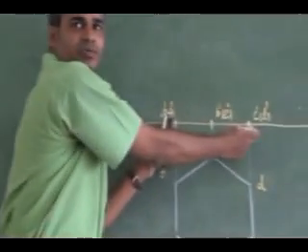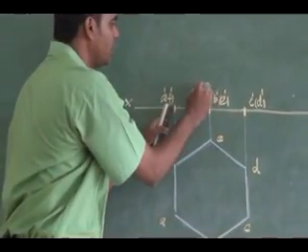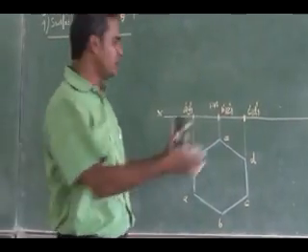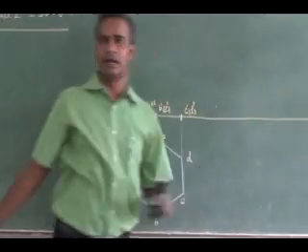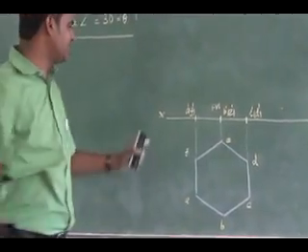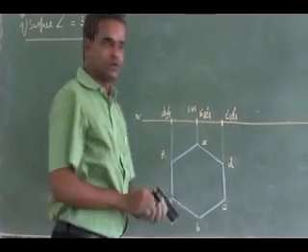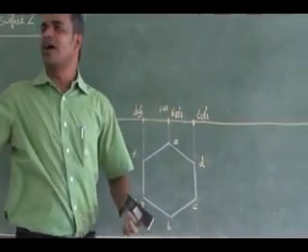That front view I have got it here. This is going to be my front view length. So the front view length I have got it. This front view length I can tilt it to what angle? 30 degrees. So I can measure this. I can reproduce this front view to 30 degrees. So that is going to be my final front view.